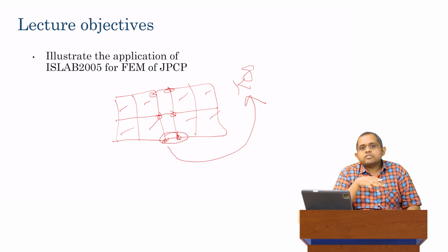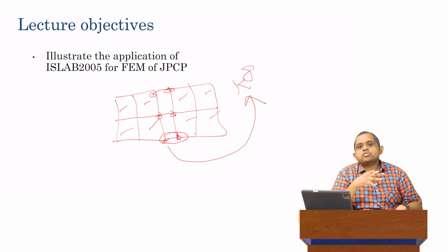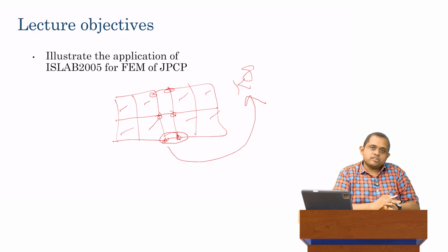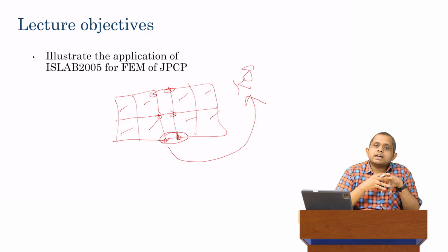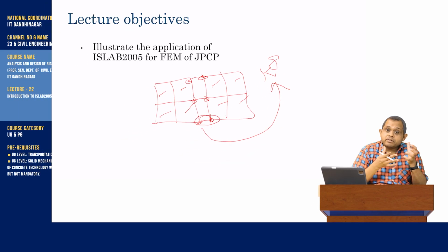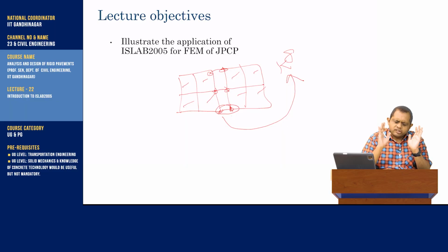So in the same stiffness matrix, we can have the physics of the individual slabs as well as the physics of the interaction between the slabs. That is really the remarkable thing about the finite element method: the ability to model multiple physics within the same system. Of course, it's approximate, so we are carrying an error. But if we try to model the coupled physics analytically, it would actually be quite a difficult problem. And as an engineer, it would probably be an intractable problem, at least for engineers.